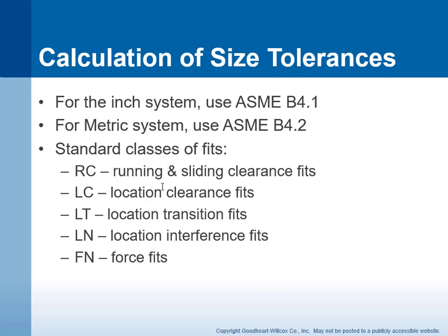RC is a running and sliding clearance fit. LC is a location clearance fit. LT is a location transition fit. LN is a location interference fit. And FN is a force fit. We touched upon this briefly in the last chapter.